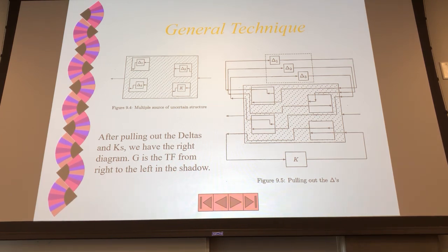Diagonal, isn't it? Diagonal. So that's why the big delta matrix may not be fully populated. It's simply diagonal. Then I can sharpen the uncertainty bound much more precisely, and the design of the control is much less conservative. So that's the whole purpose of this separation of unknowns and knowns, and hopefully while you separate these, you can get the structure out of it. And in the later part, sometimes when you pull out the delta, it could be block diagonal, okay, block diagonal.